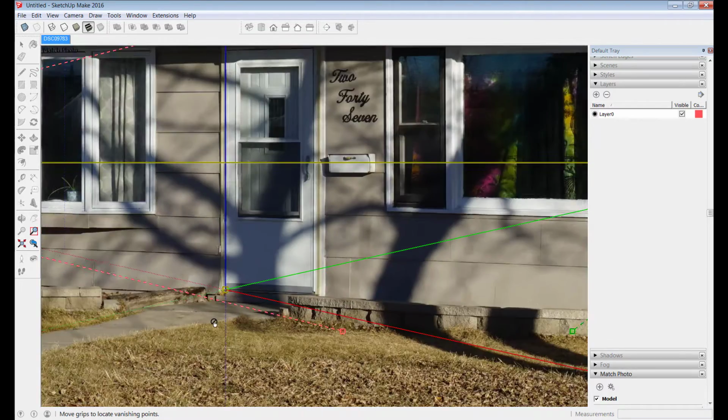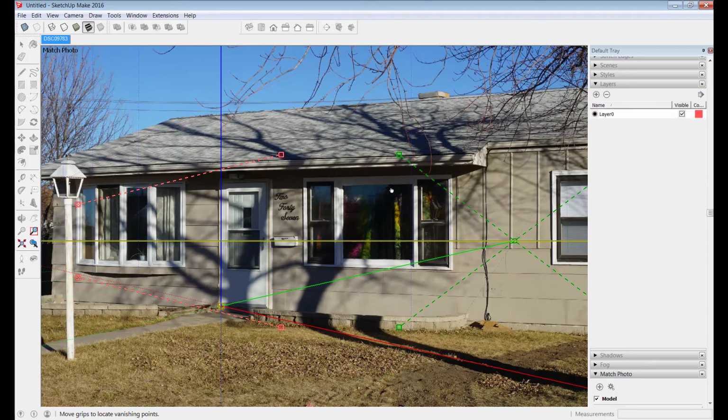You can save yourself some trouble by taking some site measurements. On this one, I thought in retrospect I should have measured the protrusion of this soffit, the width of the siding, the distance from the door to the edge of the roof, etc. But I failed to do that the day I took the photograph, and I'm just going to carry on with the tutorial to show you how I work around some of those shortcomings.